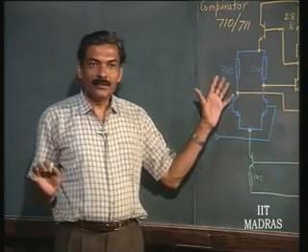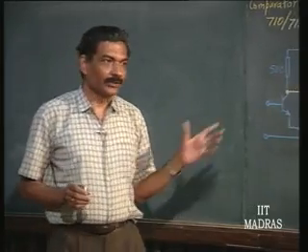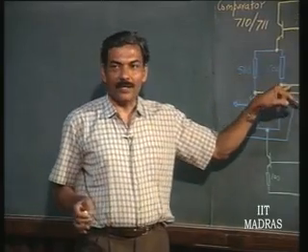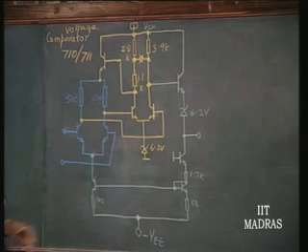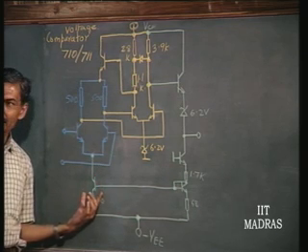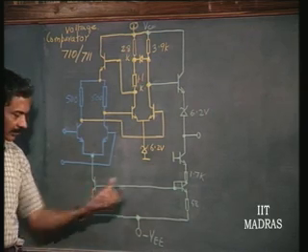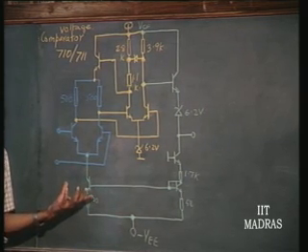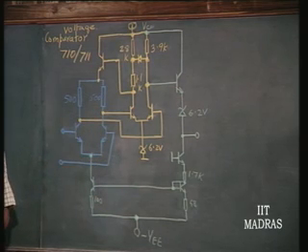Then resistors have to be made as low as possible, and therefore, we very rarely use active loads in comparators. We use physical resistances of the order of hundreds of ohms. Now, you might say the gain is going to be pretty low. One thing, operating current is not going to be low. Operating current is going to be pretty high compared to the conventional op amp. So, a straightforward current mirror technique has been adopted to obtain currents of the order of maybe milliamperes. Apart from that, the resistances are low. So, the gain of this stage is going to be very low.